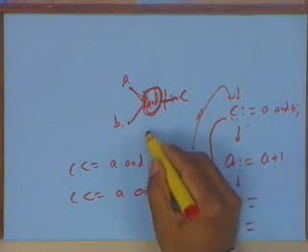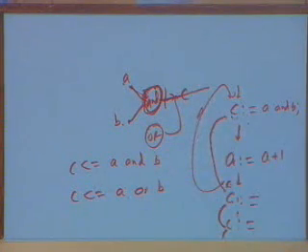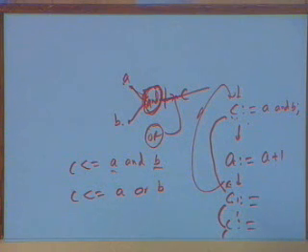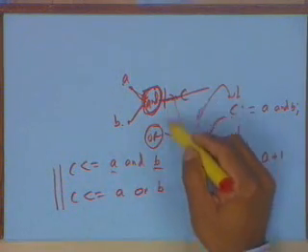Because what it means is I have another OR gate, another driver, and I connect this to this. These two drivers are getting connected to the same signal. So you have to think of these as waveforms, and you don't have to think of them as storage elements. These are nodes of a circuit. That's how we have to think. There are of course ways of specifying this, but then you have to give some resolution logic.